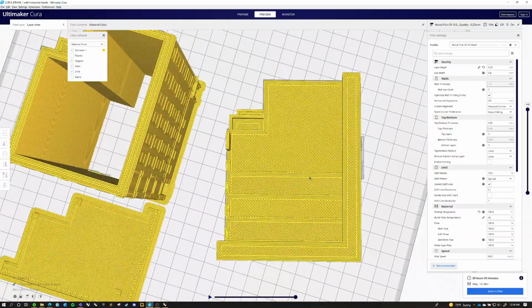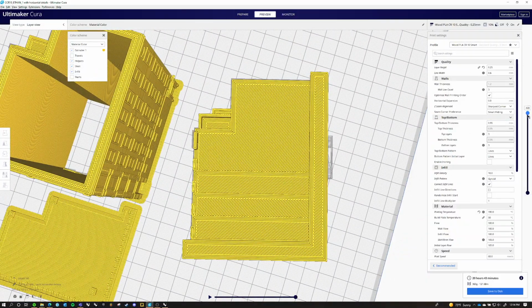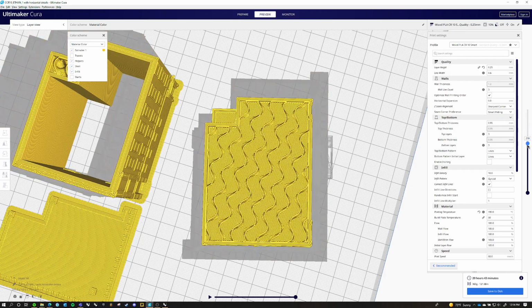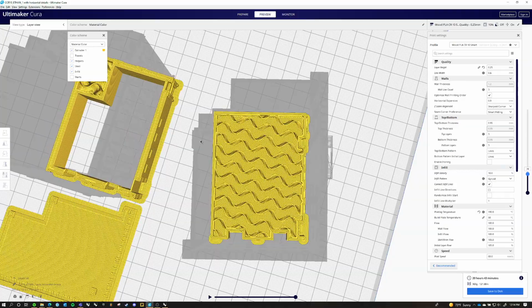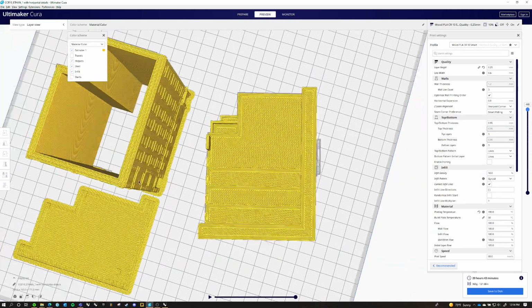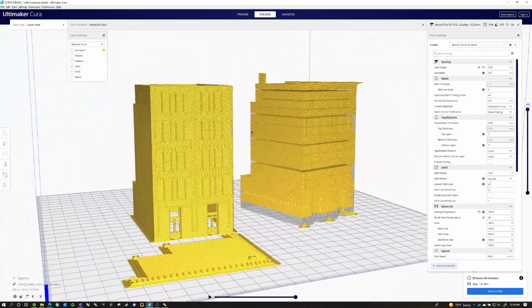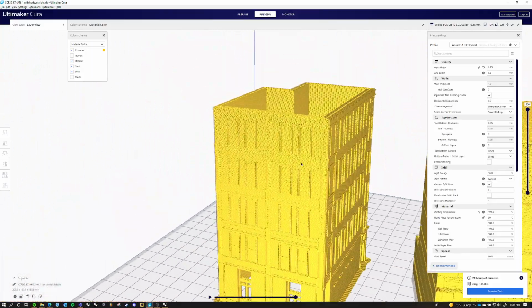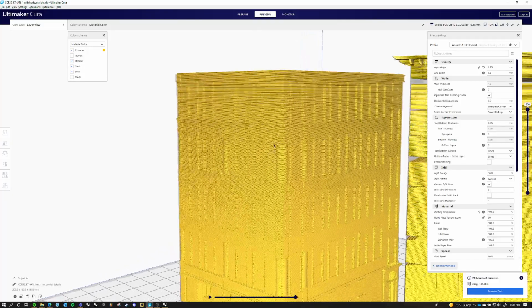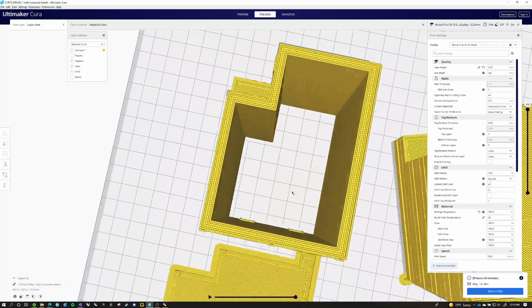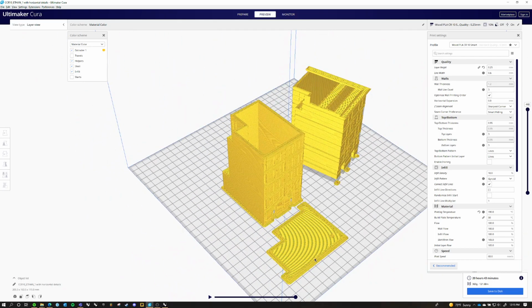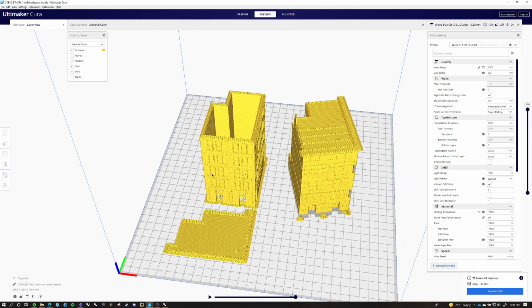And also it's solid, which makes it take 4 times as long to print. So what we're trying to do is make the detail a lot more noticeable, make it hollow, and also orient it in the right direction. That way we save time, we get a lot of detail, and the printer likes to print it.